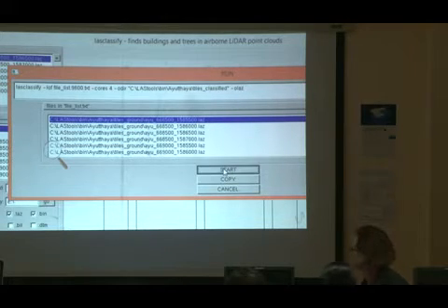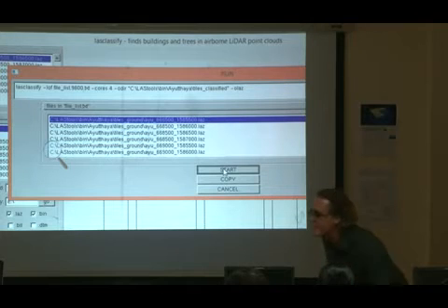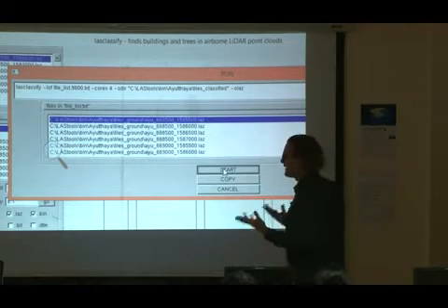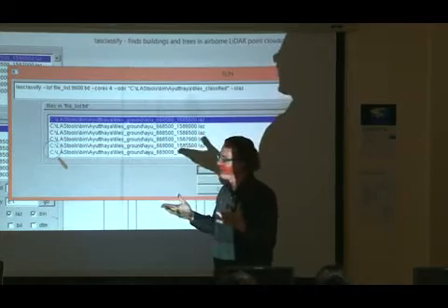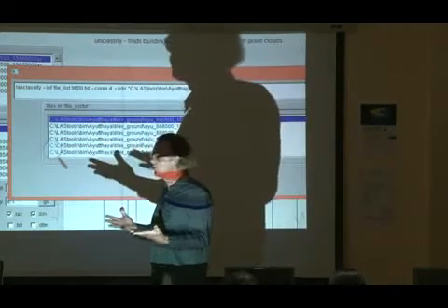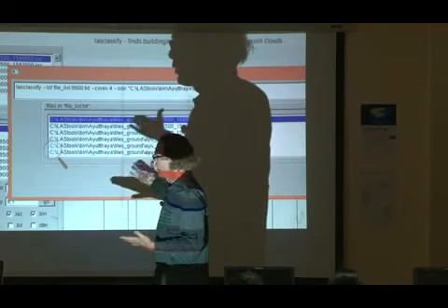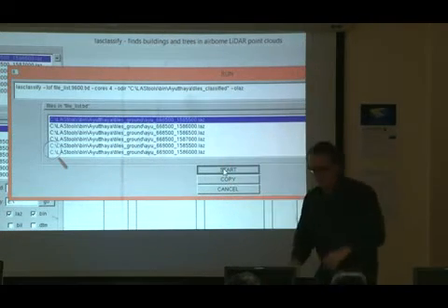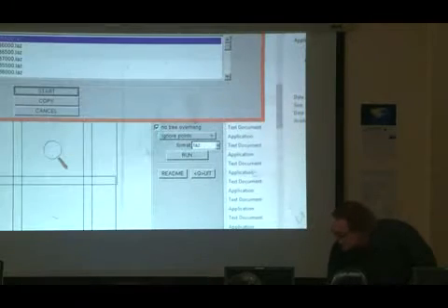And I'm starting that. So lasclassify I haven't explained yet. What does lasclassify do? Lasclassify tries to come up with some smart yet simple way to classify buildings and trees. How does it do it? It looks for all points that are higher than 2 meters above the ground. There is an option where you can change that.